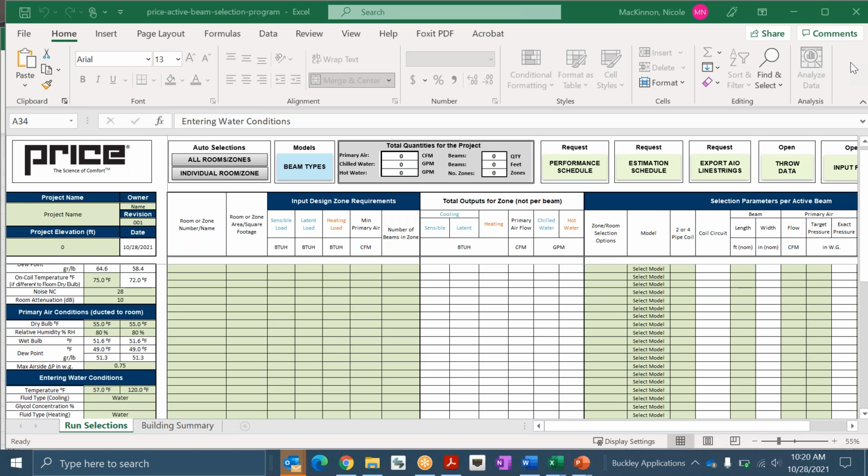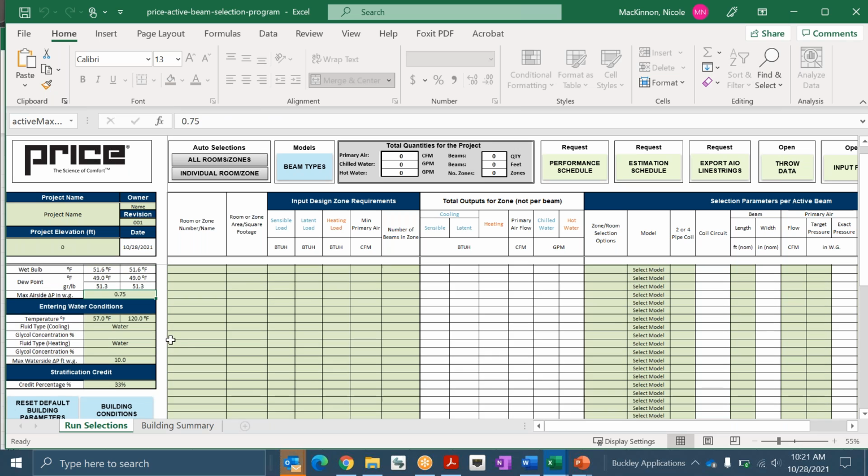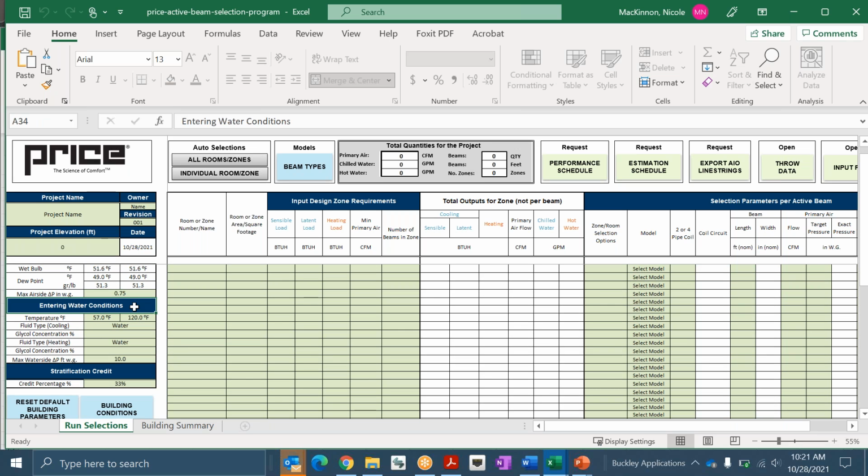Yeah, great point, Ed. We typically just have a range of static pressures, 0.2 to 0.8. To recap what Ed was saying, the threshold on the bottom side is to make sure that we know what's induced through our water coil. And the upper end is what your system can actually produce, and also what's going to be dictated by your noise levels. So we'll go through some selections and show the effects of that as well. Those are all great points. So that's the last thing on the air side, the static pressure target range, the max upper limit there.